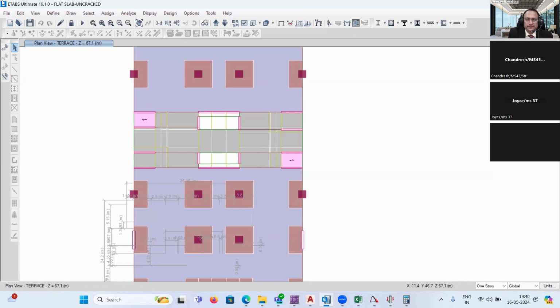Right? 16-story building. Sir, was it even possible to reduce the thickness of the slab and then give a pre-camber? Yes, pre-cambering and all can also be done easily. And the thickness, I'm telling you, the drop panels also can be 600. And the RCC slab also, instead of 300, you can go up to 275. 300 also is okay. We have given 300 slab thickness for flat slabs in many places.